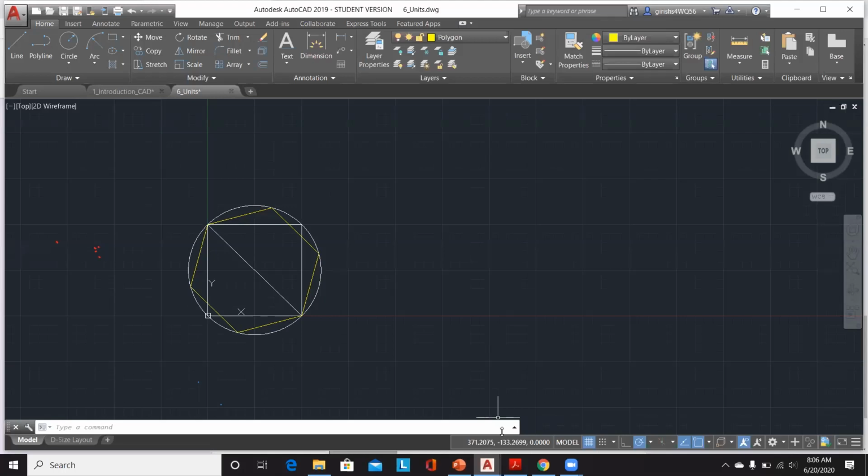If you are reducing your drawing from millimeters to inches, you will have to apply a scale factor of 1 by 25.4 to make your model as accurate to the scale that it was drawn before. For example, if your drawing is 8 inches in imperial units, with the scale factor it will be 8 times 25.4 millimeters. It is to the scale drawn with the scale factor.